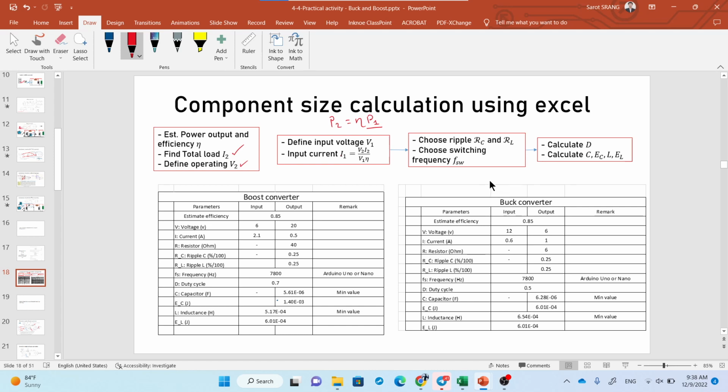All right. Oh, I think I missed one thing. The frequency of the pulse, PWM, pulse width modulation, you need to choose as well. And the recommended range is 1 kilohertz to 62 kilohertz. Cannot be more than this and should not be lower than this.